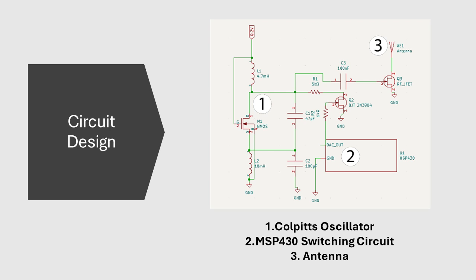The way we use frequency shift keying to encode our information is through shifting energy from the 915 megahertz band of the electromagnetic spectrum 200 kilohertz over using the oscillator. We do a sort of on and off keying in which energy appears and disappears at the 915.2 megahertz part of the spectrum, and we assign a set data rate. This data rate is the set number of bits that would be transmitted within a second.